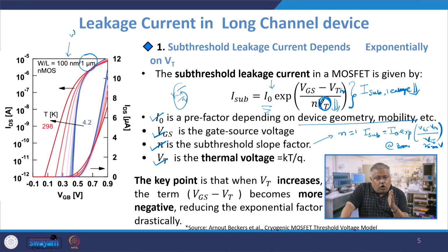But if you operate your gate voltage, which is the signal giving voltage, above 0.6 or below 0.6 approximately, you will see that the subthreshold slope is much changing. Beyond threshold, when you go beyond threshold, you see the blue color slope is much higher, and when you go below threshold, the reverse is correct, right, and then you can predict therefore the subthreshold slope will go on changing beyond a critical point.